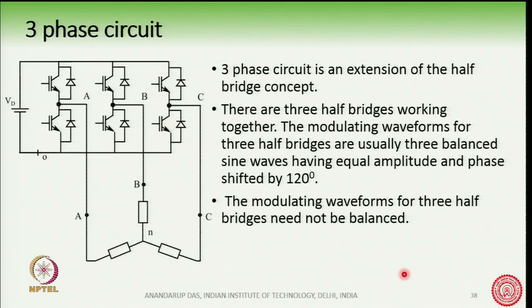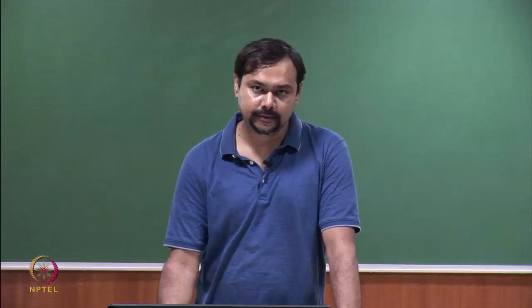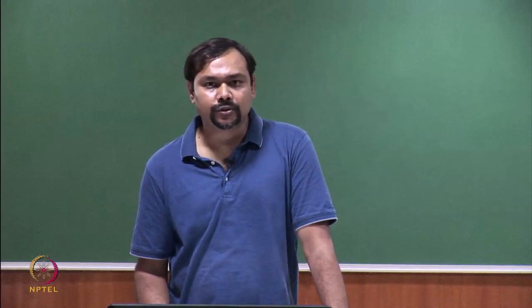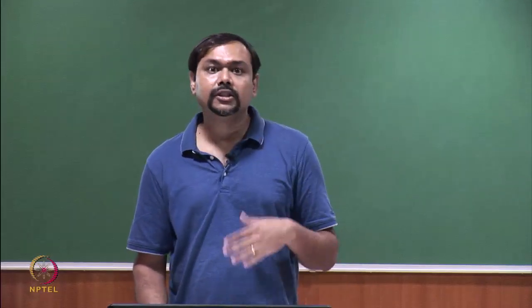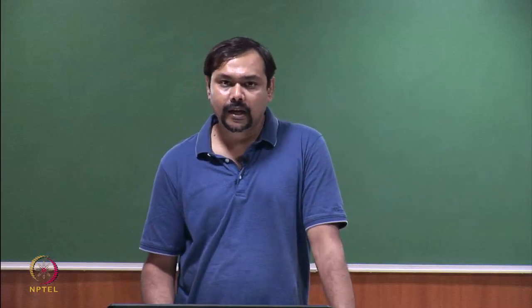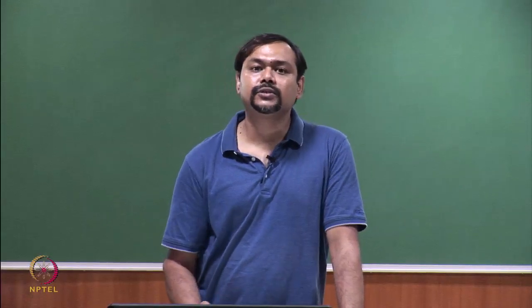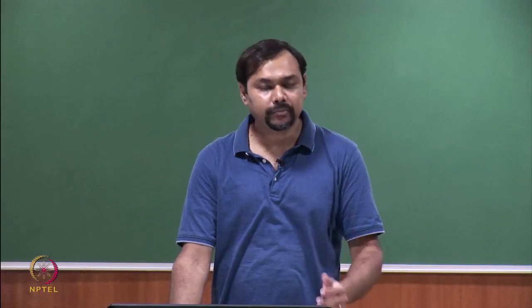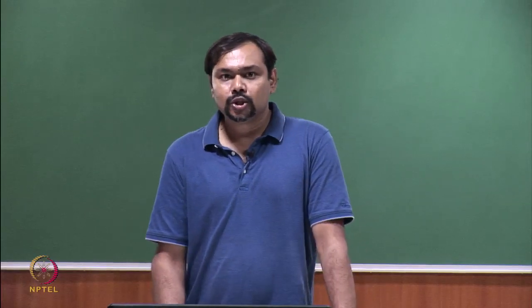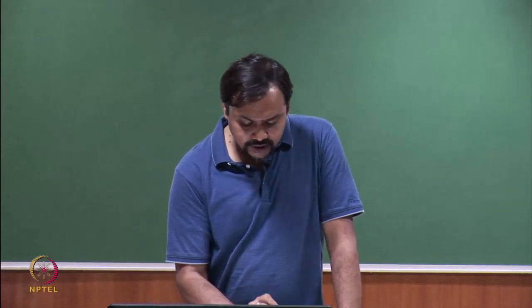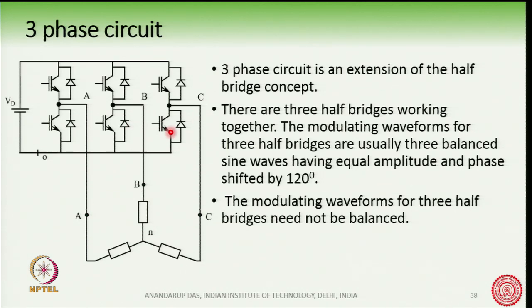There is no requirement that these 3 waveforms have to be balanced. They can be unbalanced also. In fact, when such a converter is used in an unbalanced system, then it may be required to produce unbalanced voltage waveforms from this converter. So, these three half bridges usually operate with balanced reference waveforms, but they can also operate with unbalanced waveforms.